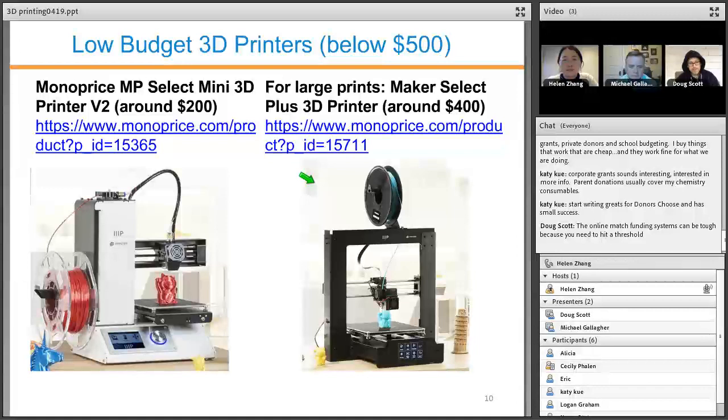And to be honest with you, I have found through the vendor that I buy from, the PLA filament prints best. And I've even made it more finite where the translucent colored ones that I buy, so if I buy translucent orange, it will print better than solid orange PLA. So I found that those translucent PLA colors print beautifully. And if we need to, like that kid with the train, he wanted to paint his gold, we just painted it. That was fine.